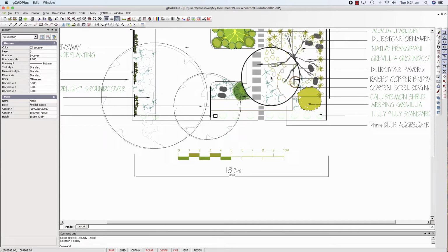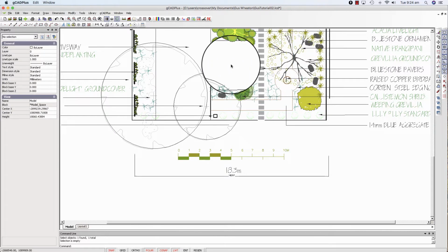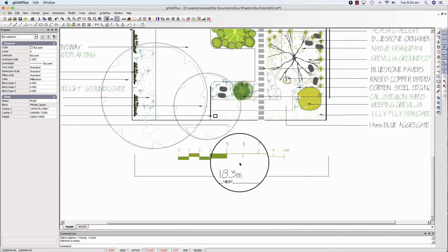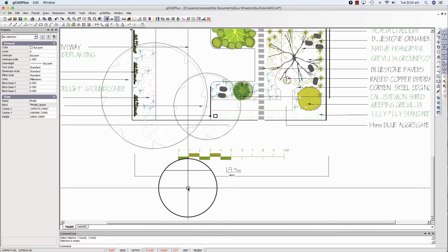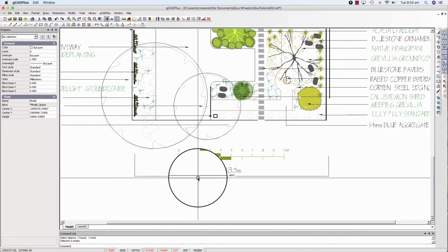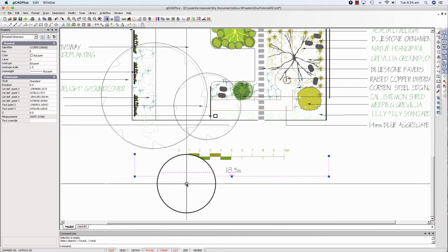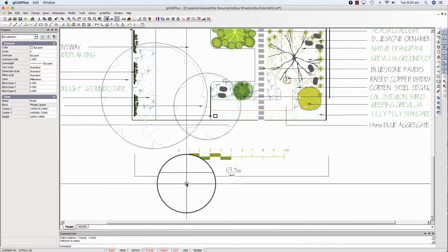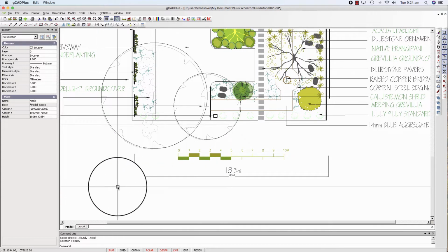We are looking here at part of a concept design for a site, and we're looking here at the front garden area, and the width of the site in this design is indicated by some application of some dimensioning. Our preference is to put the dimension information on a separate layer, because then it can be turned on or off within floating viewports in layout space.